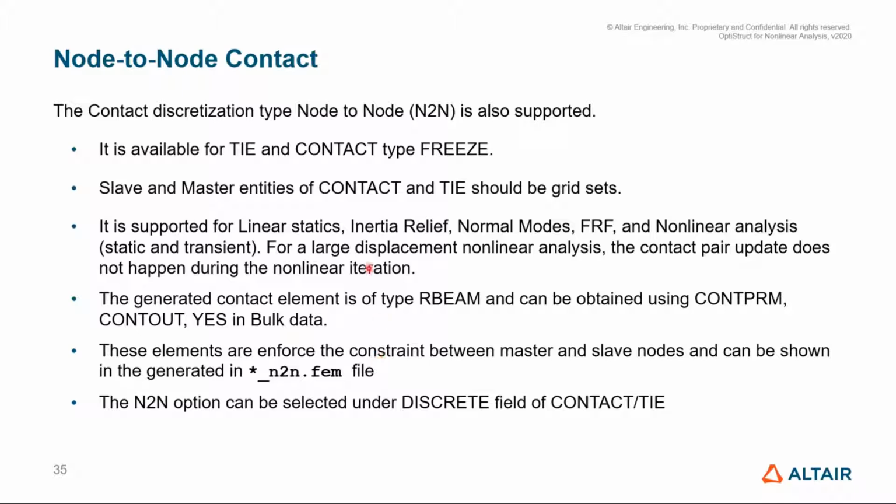It's supported for linear, and it is supported for non-linear as well. Large displacement is supported, but it will not update during the iteration. It means that you will establish that contact, but it cannot separate during the large displacement.